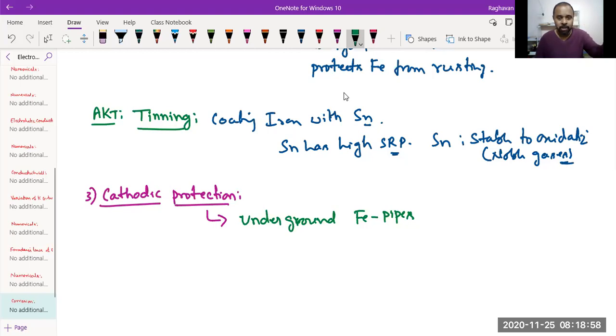That's why the vehicles in the coastal areas, their body will be more corroded than the vehicles in the non-coastal areas. For example, if we go to Mangalore, the weather has a lot of sultriness and humidity, which contains salt in it. So the chassis and everything may be affected at a little more rate than other places. So going for a second-hand vehicle from coastal areas is a risk, so you have to examine properly. That's why, especially in coastal areas, the underground chassis will be coated with a polymer to prevent corrosion. That is also done.